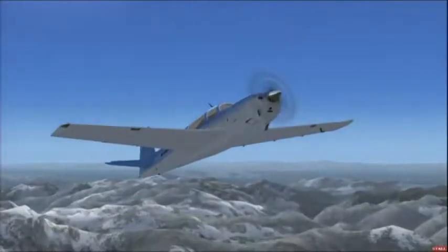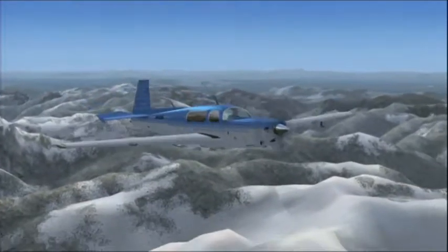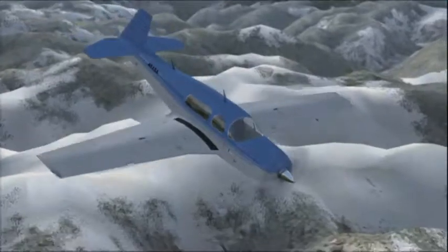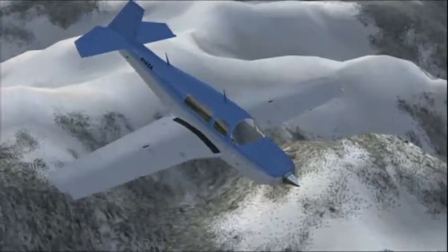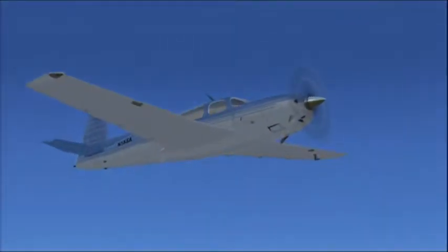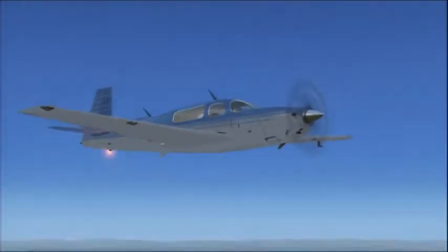To summarize, the critical angle of attack can be reached at any airspeed, be it in straight and level flight or a 60-degree bank. You can reach that critical angle of attack at any airspeed at any attitude. The flight attitude is the attitude of the airplane in relation to the horizon. It can be in a climb, nose-down attitude, or even straight and level flight. The airspeed at which a stall occurs is determined by the weight, load, and the altitude.